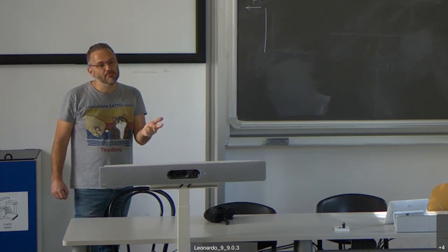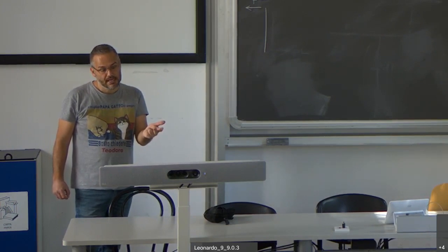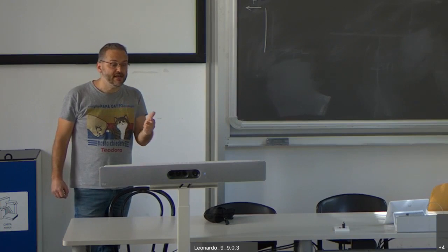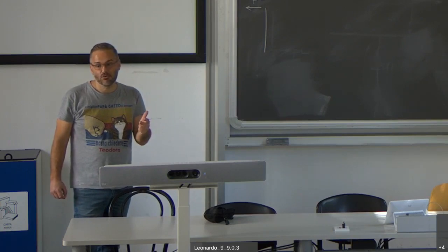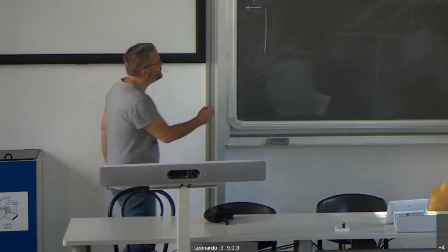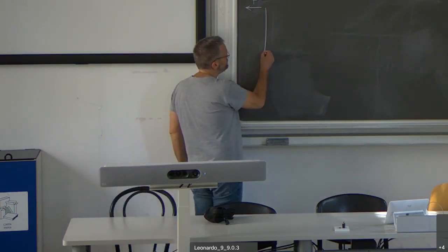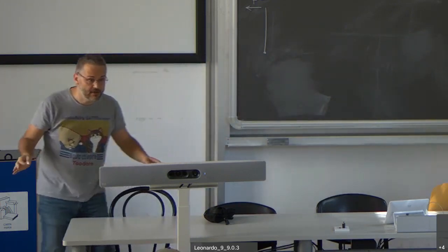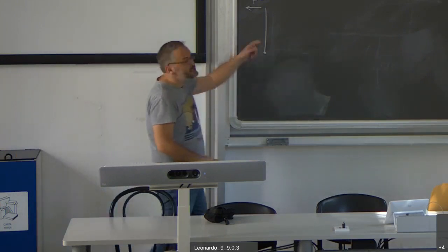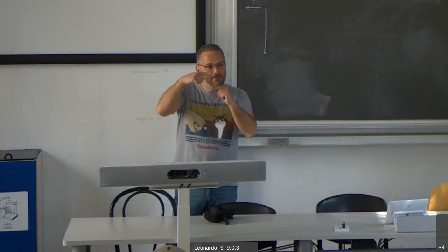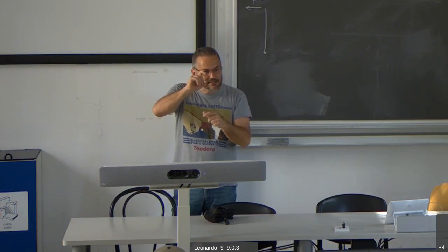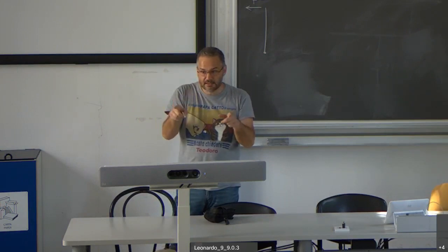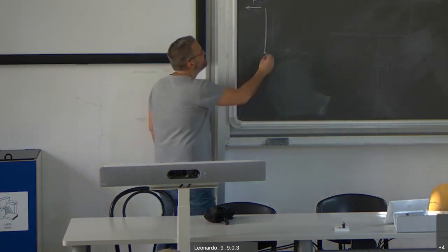Bending moment diagram will be zero, constant, or linear. So the worst case, the more complicated case, is when I have a linear diagram, which only requires 2 points. Which means that if I have the internal forces here, I have everything I need, okay? So instead of working on a single element of the beam, the X element, the way Maria Chiara did it, so you have it in your solutions, I will look at the whole member.